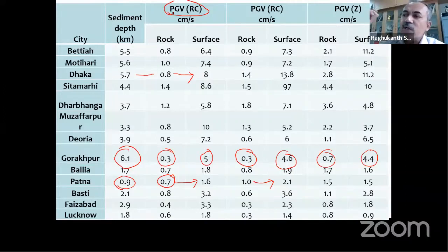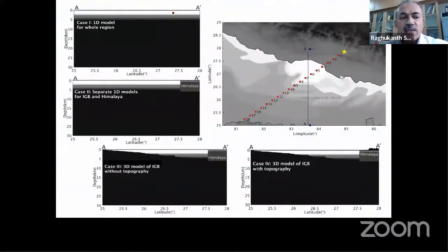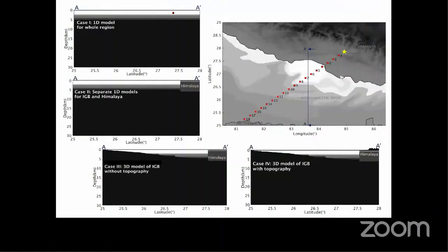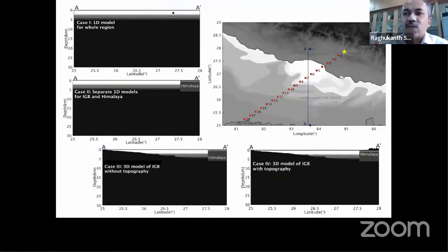And as I already mentioned, the data also say that NGRI people have estimated velocity amplification of almost 5 to 15, and our simulations also give the same for velocity. Now, to understand this basin, we have done some simulations, because once the computational model is ready, we can do all these things. So to understand soil amplification and basin amplification, we created several models.